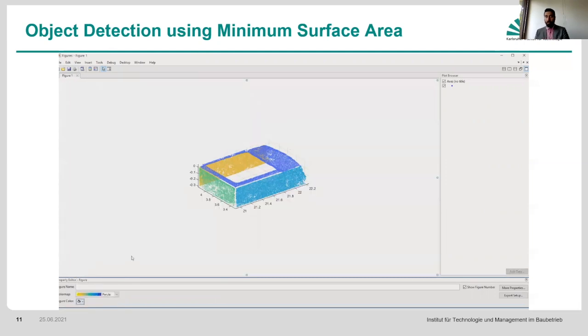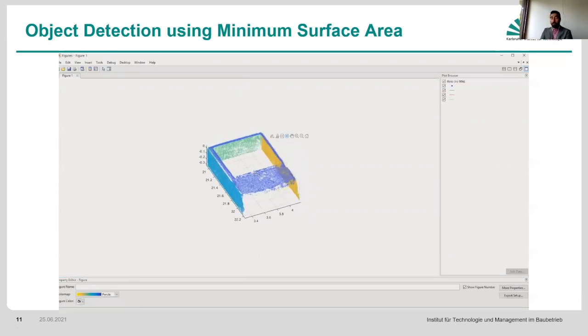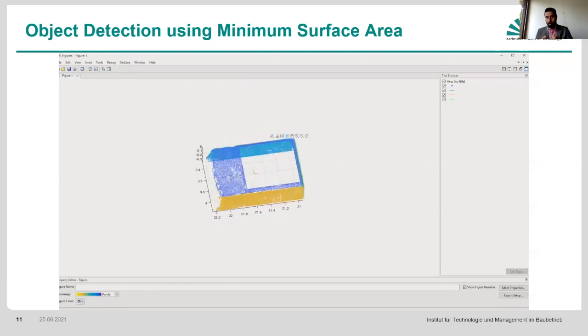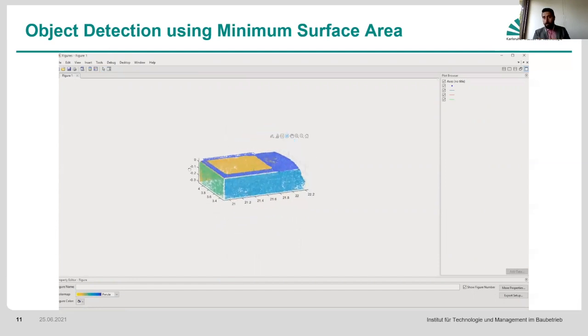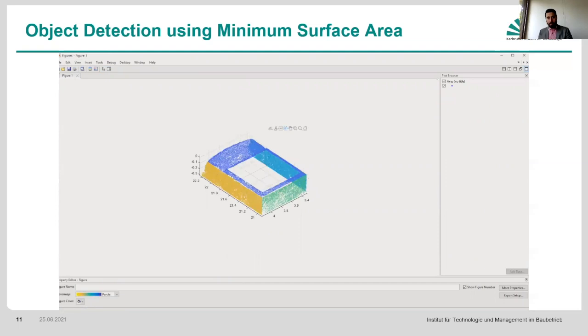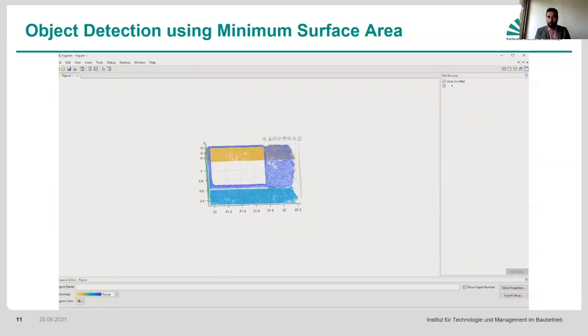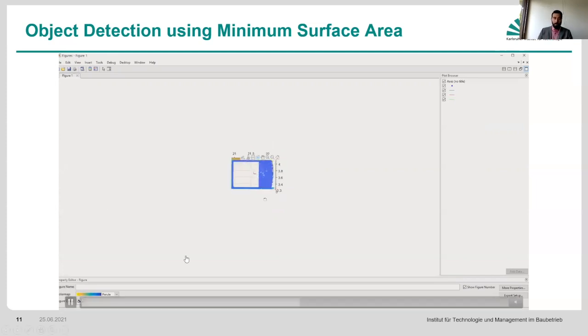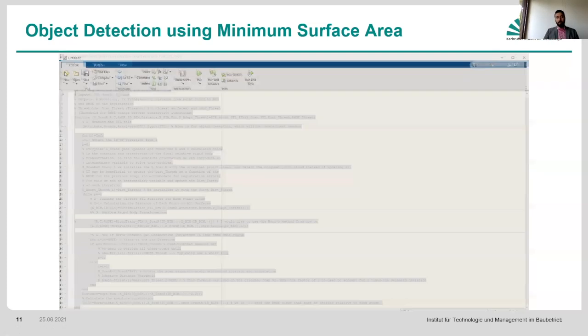And this is where you can color code it and show that this group of points belongs to this surface, that group of points belongs to that surface, and these are different from each other. You can segregate them from each other. If you didn't have this ID of surface, you had no option to do that. And the good thing is the way that we had performed it strategically, we just used the same calculations and added another variable, which gave us the ID_surface.